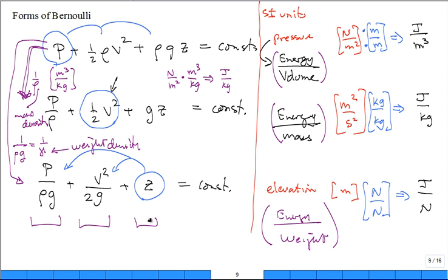This is the potential or gravitational potential energy. Along a streamline, same chunk of fluid, steady flow, no heat, no work, inviscid, no friction to slow it down and make it hot. There you go. It's incompressible, and the sum of those three forms of energy, they can be converted between forms, but the sum is equal to a constant.